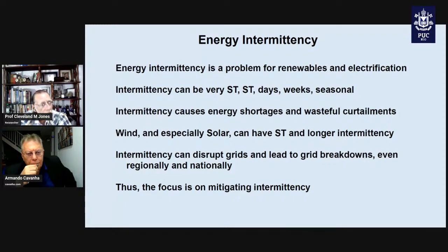But if you're talking large projects, it's going to be very difficult because intermittency means that you might have zero generation. And if you have a 1 gigawatt project and you have zero generation, you have to have 1 gigawatt of contingency power available. And even if it's for a short duration, that means a significant storage capacity.